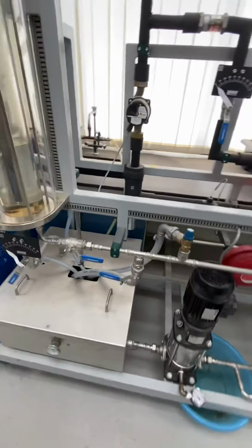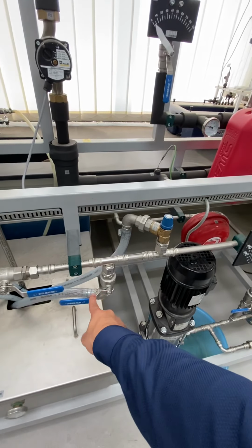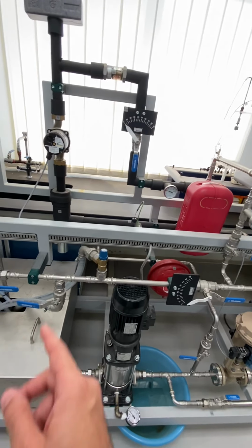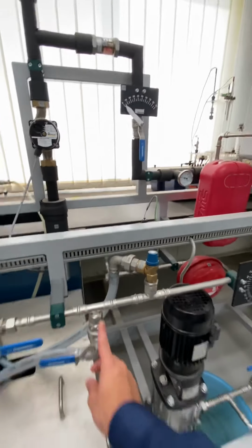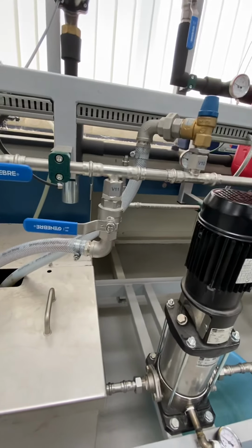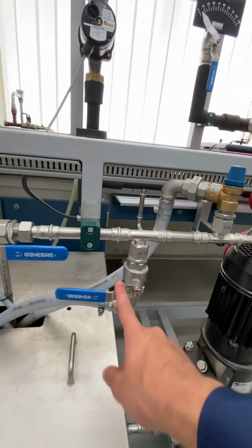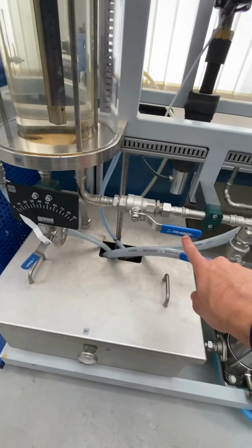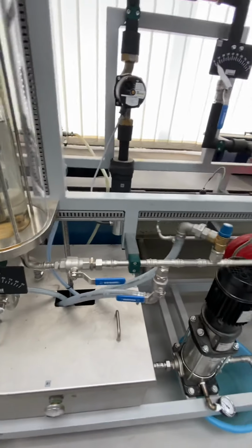And yeah, speaking of how to tell if the valve is fully open or fully closed, guys, it's very simple. Just look at the handle and try to see what angle the handle makes with the pipeline. If it makes a 90-degree angle like this, then this means that the valve is closed. If it is parallel with the pipeline like so, like V12, this means that the valve is open.